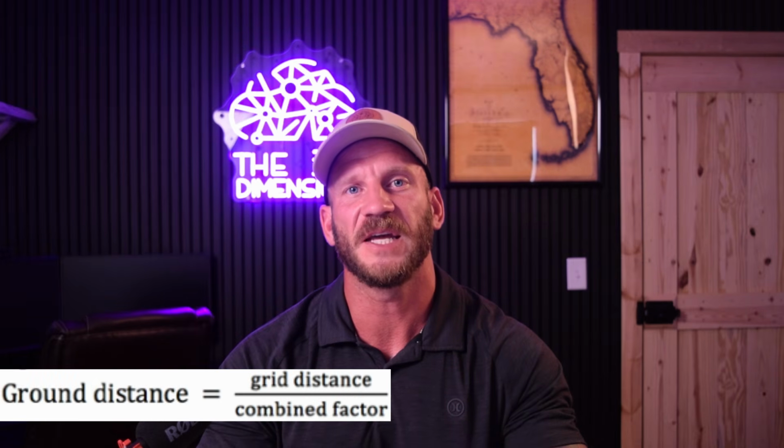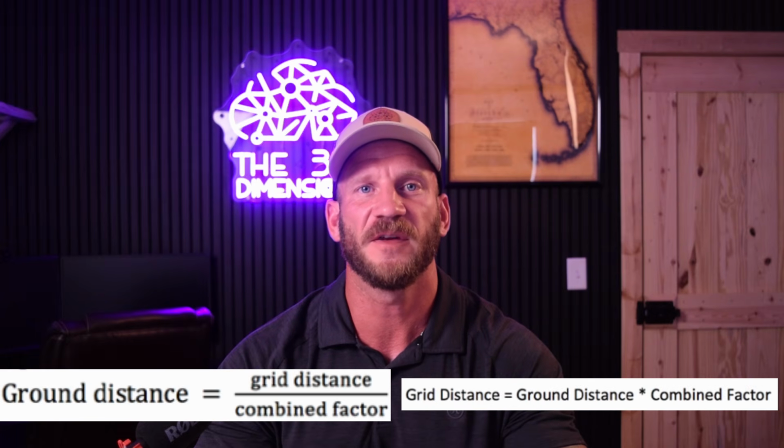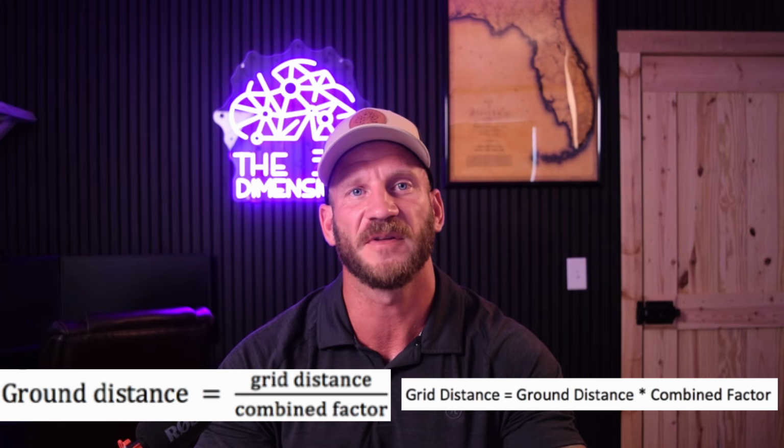We approach these scale factors as a two-step process just to give you a clear picture of what each one does, but in reality they can be combined into a single step conversion. Ground distance is equal to the grid distance multiplied by the inverse of the combined scale factor, and grid distance is equal to the ground distance multiplied by the combined scale factor.